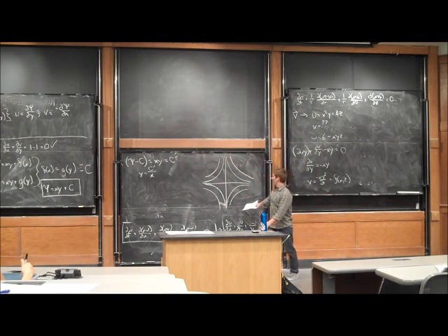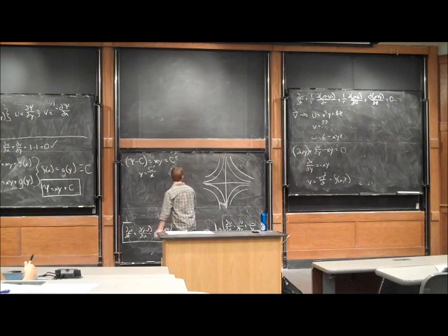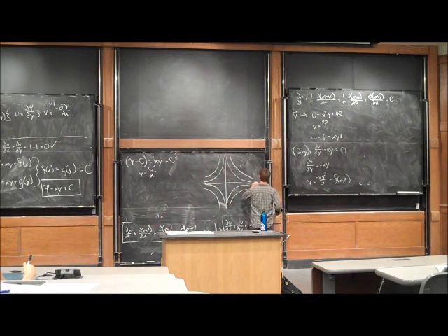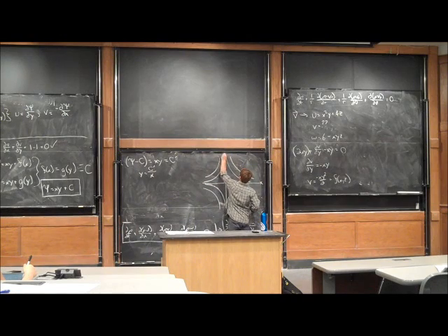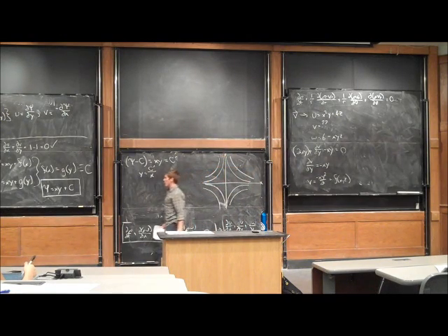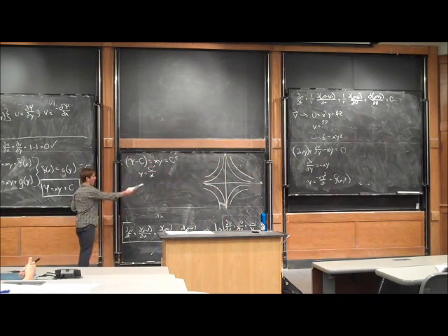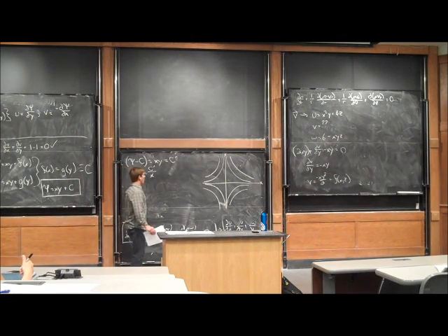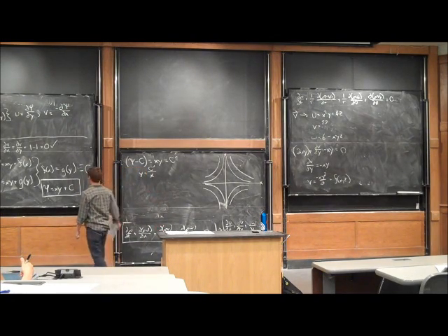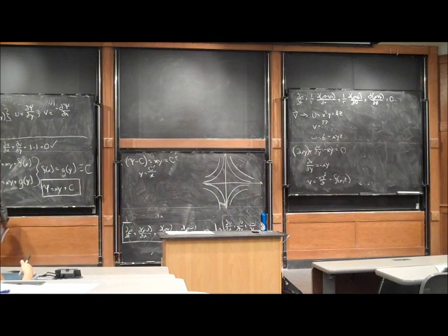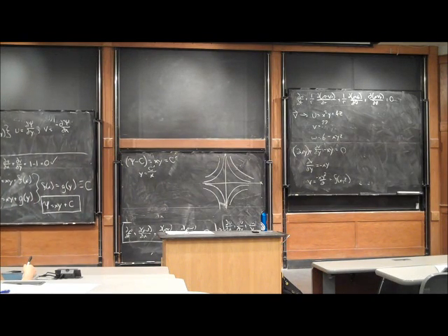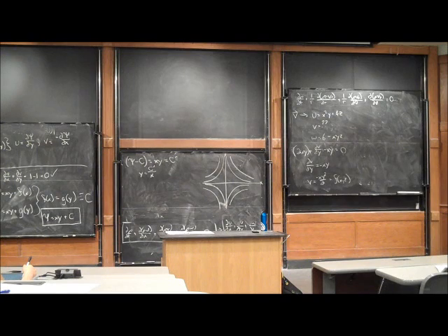But these are streamlines. So these are just functions that we plotted, but because it has to deal with a velocity field, they have a direction associated with them. If fluid is flowing along these lines, it's only flowing one direction. To figure out what that is, I have to go back and look at what I defined my velocity field to be. So I know that whenever x is positive, my velocity field should be flowing in the positive x direction. So I can look at that, and I can say that this must be this direction.